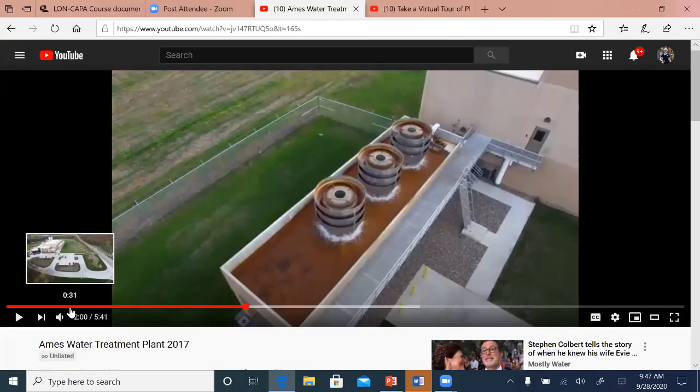Also in many cases, for instance, the East Lansing system, the MSU system, iron and manganese levels in the groundwater are quite high. And often we want to remove the iron and manganese in order to produce higher quality water. Now we can use an approach like MSU is using with an ion exchange system. But the system that they've chosen at MSU doesn't remove hardness. It removes iron and manganese, but it's not going to remove hardness.